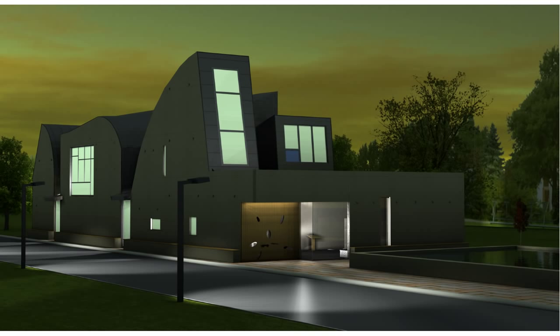The second thing we need to do is make objects glow. You can see with these windows here, there's a transparent surface tile assigned to those, and there's a glow parameter. So each of the materials that you have, there's a glow option. You turn the glow up, and it makes objects glow. It's not a light source, but when the scene renders, it looks like that material is glowing. Now, you can assign an actual glow to a light source. I'll talk about that in just a second.